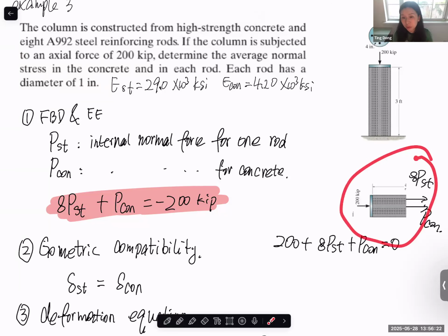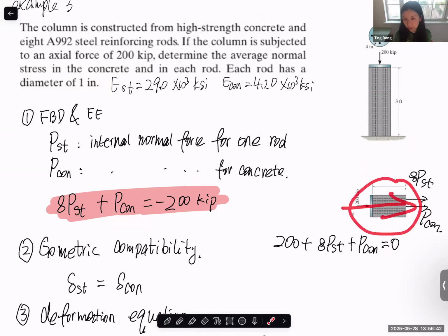So when we do the free body diagram equation like this, we are not assuming anything in compression or tension beforehand. It's purely based on you cut the random point of this structure. That is how you find the internal normal force. Since you guys get used to anything in the x direction, that's why I rotate in the x direction. Now this is facing the positive x direction. And based on sign convention, check notes in the statics review of the first class of this semester, when this is a positive plane, positive surface, the sign convention for internal normal force is positive.